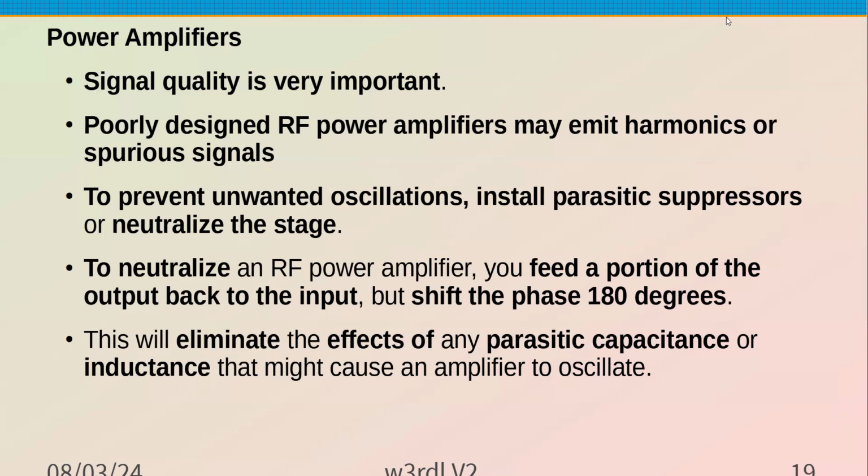Okay, so you care about signal quality, care about harmonics, because the FCC won't approve the device unless the third harmonic is down below. I can't remember the exact number. It's around 40, 42 or I don't know. And they've changed it.